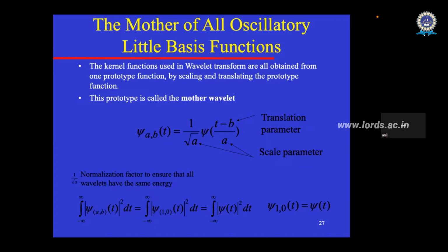If I tell you the wavelet meaning now, you will appreciate it more. Wavelet means small wave. It is not from minus infinity to infinity. It is only for a limited time. The beauty of what the wavelet transform says is that if you choose a mother wavelet properly, which follows these conditions, you can represent any signal with the scaled and translated versions of this mother wavelet.